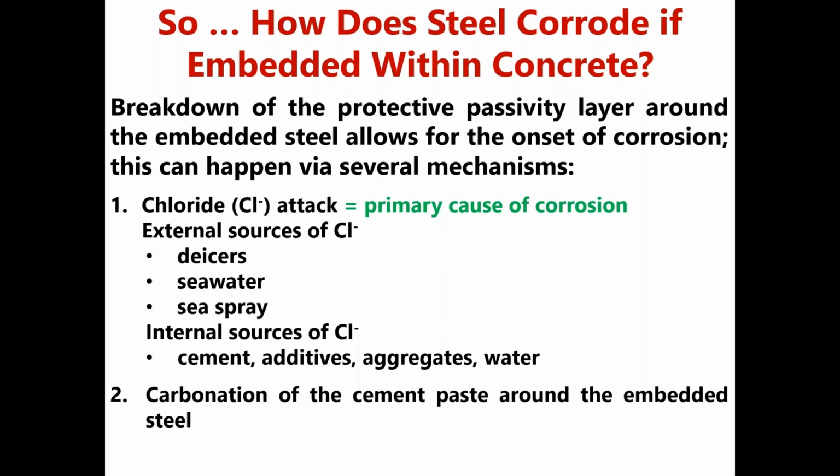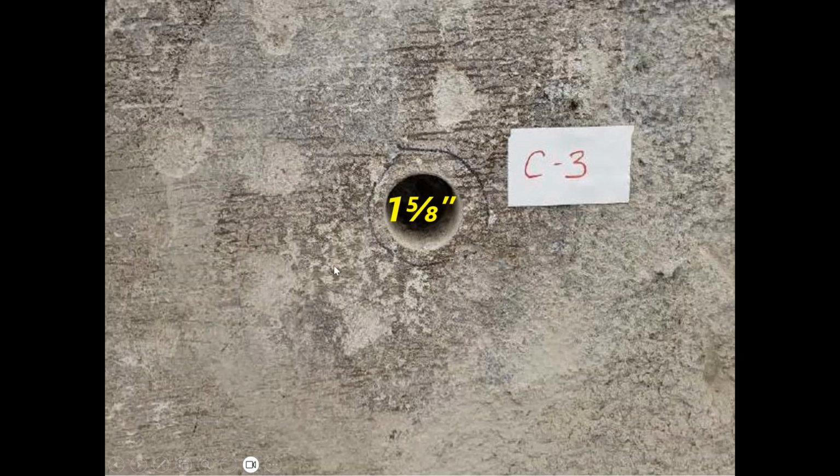So in a couple words, you carbonate cement by introducing carbonic acid into the paste. Carbonic acid is naturally formed from water and carbon dioxide. It's dissolved in water. That water with the carbonic acid gets into the paste. It interacts with the portlandite within the paste, and changes it to the mineral calcite, hence the term carbonation. So in the process of doing that, it's lowering the pH of the paste.